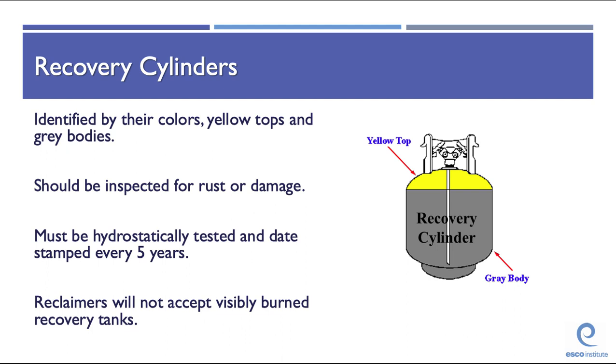All refrigerant recovery cylinders should be inspected for rust. If a refillable cylinder shows sign of rust or appears to be heated or damaged in any way, it should be reduced to 0 psi by recovering to another cylinder and discarded. Reclaimers will not accept visibly burned tanks.